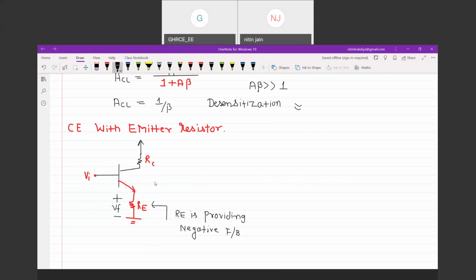So what is the polarity of these two? You can say Vi minus Vi plus Vf is equivalent to 0. So this input and feedback have different signs. So this feedback is a negative feedback. Right. That is the mathematical way to find it; otherwise we had a discussion of how this stabilizes the biasing point of the transistor. So this is the idea for the circuit.